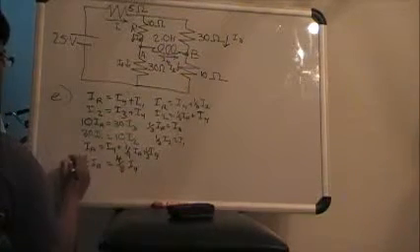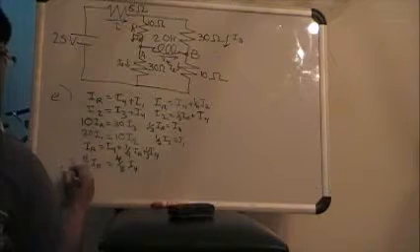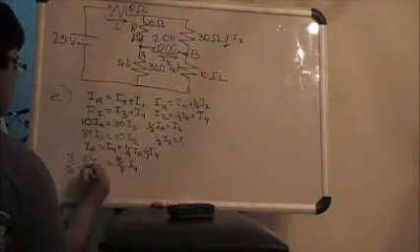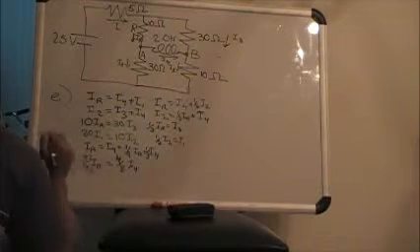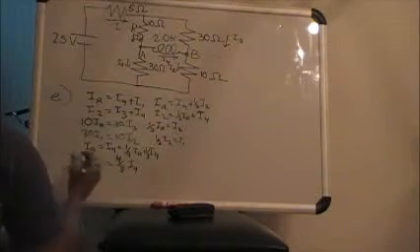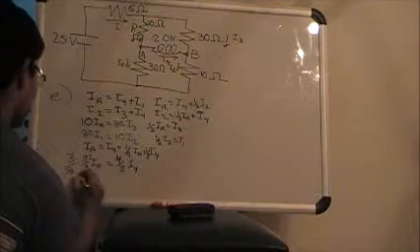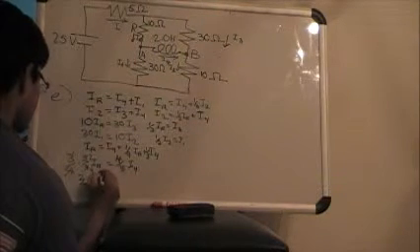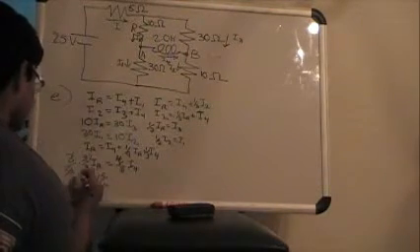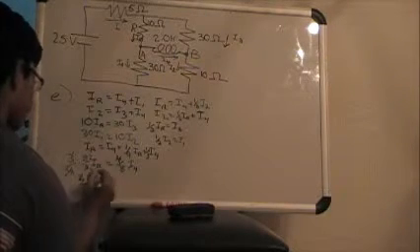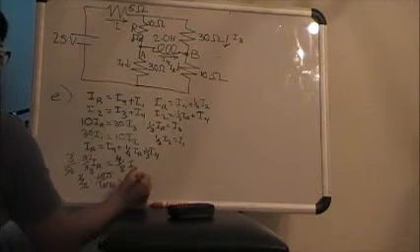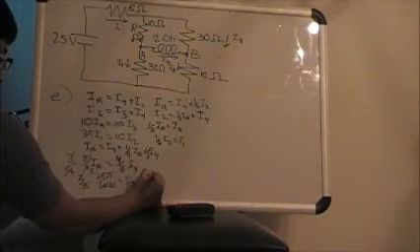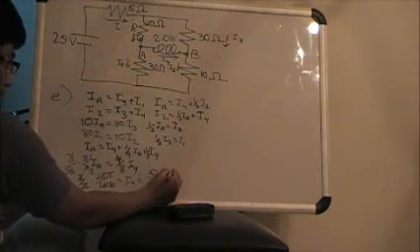Then when you take this to this side, so 3 out of 4 times that, you cross out 2, cross out 3, so 2/3. Then you have to remember that IR from part B is equal to 15 out of 16. So 2/3 times 15 out of 16, and that cancels out to 8 and 5, is equal to I4. I'll just rewrite it again, is equal to 5/8 amperes.